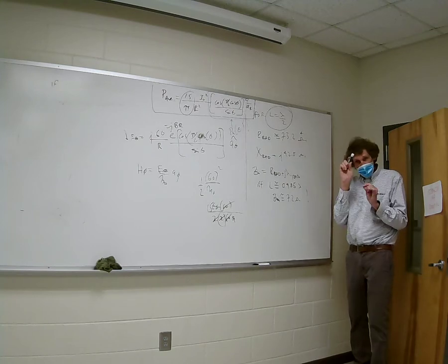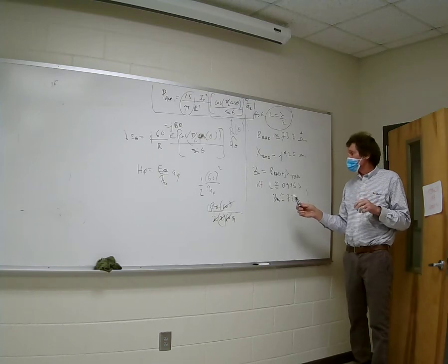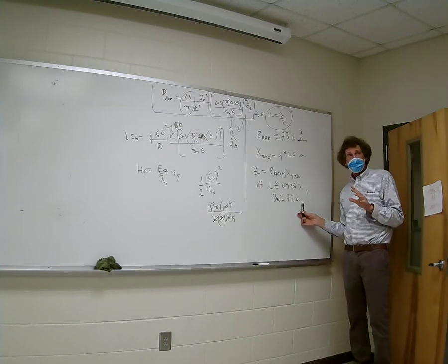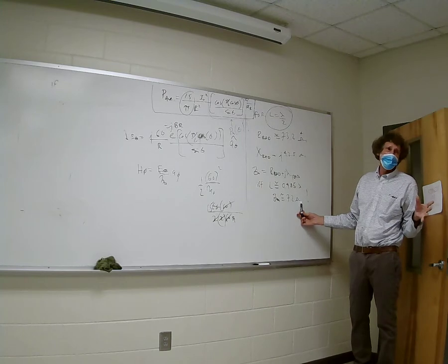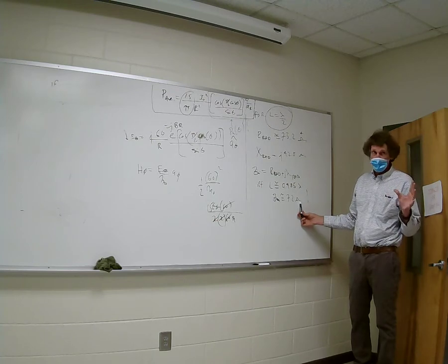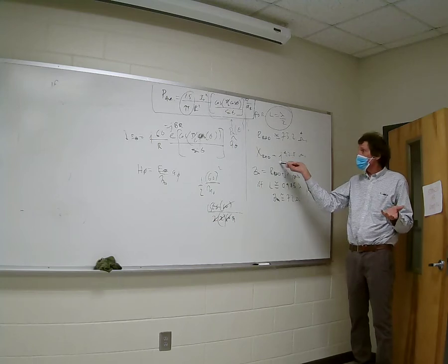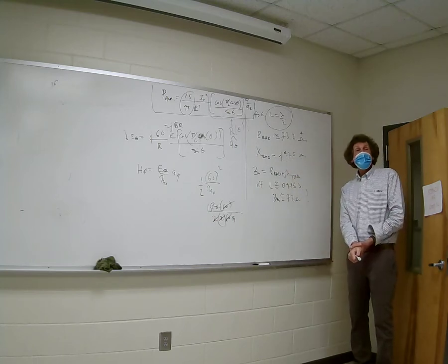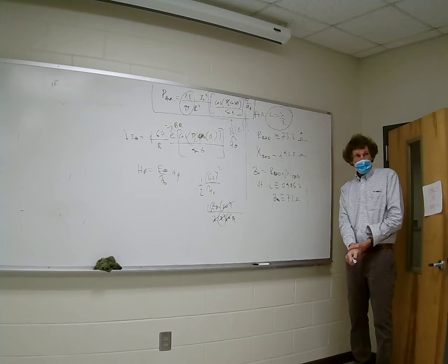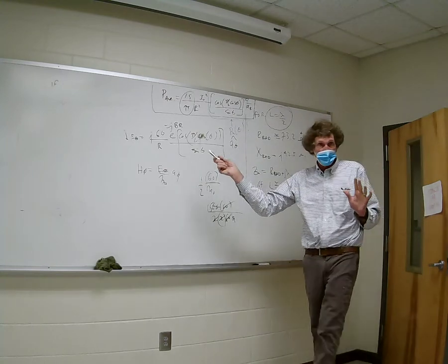But if we just cut it down a little bit, the driving point impedance becomes strictly real at about 72 ohms. Now in his book, he's going to have 73, something like that. It's really a little less. It's about 72, and it does vary somewhat on the radius of the wire. Follow me? Now, here, you get rid of the imaginary component. So now it takes the least possible amount of voltage to get the most possible power when it's cut just a little less, and there is no appreciable change in the electric field. Y'all hear me on that?